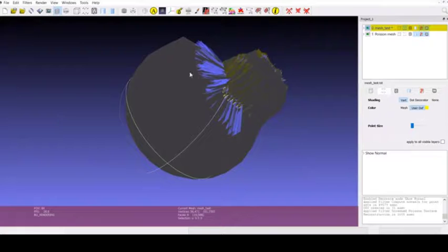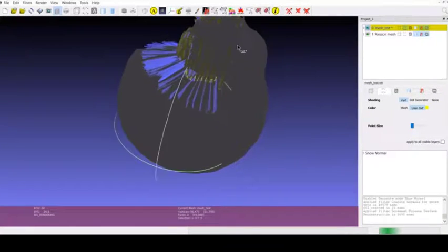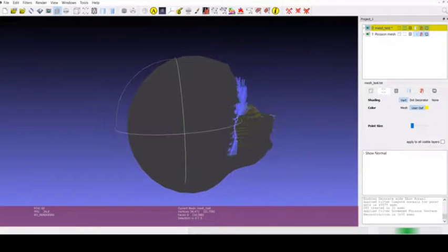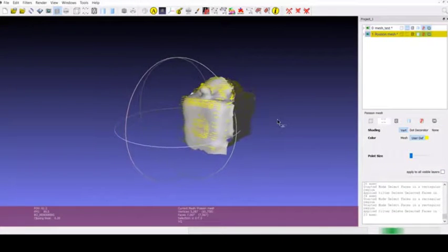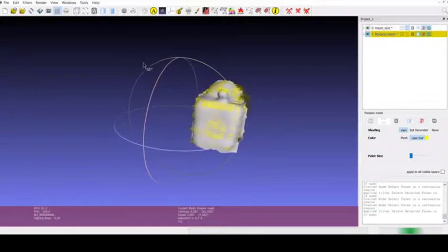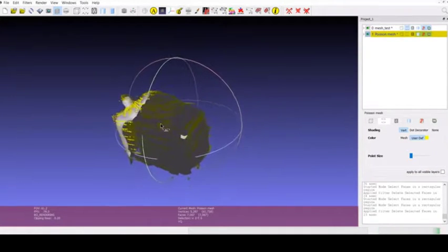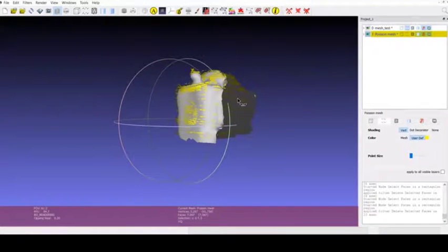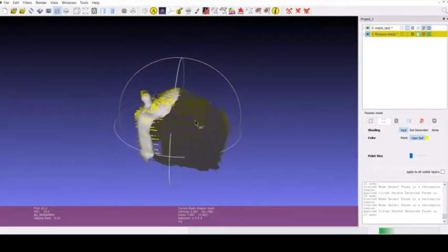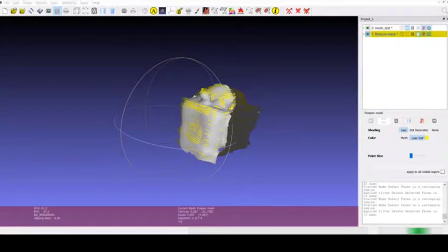So we're going to clean it up. Delete a bunch of these surfaces here, and try to clean up the back and make it a flat surface down here. It kind of bulges, and then start to clean up the big bulb we had before. I cut away a bunch of the pieces and cut off some of the base. But we can see here how the general map of the Testudo 3D point map matches the mesh that was created by MeshLab. So next we'll put that into Creo and make a base so that we can actually 3D print the part.